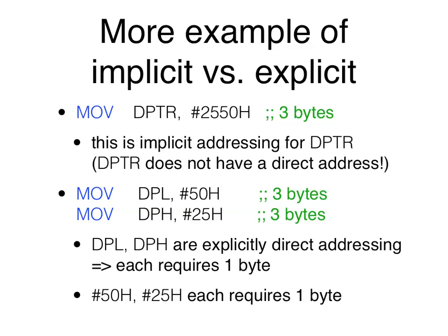And this actually is pretty common. It's not even limited to 8051. Even if you go to ARM, or many other architectures, they also have ways of working with these larger pointers. Could be 16-bit, could be 32-bit, but the larger register itself does not have an address. Instead, you have to load the individual bytes of that larger pointer or larger register.